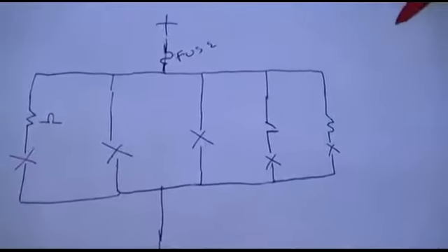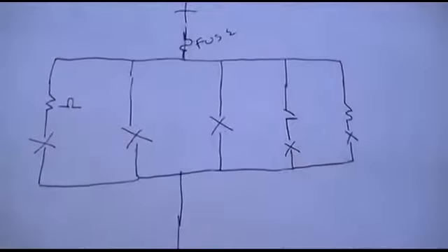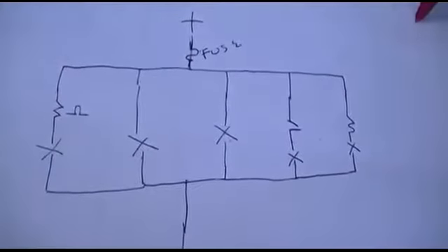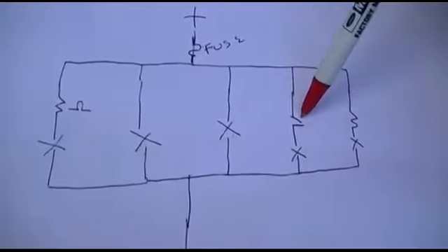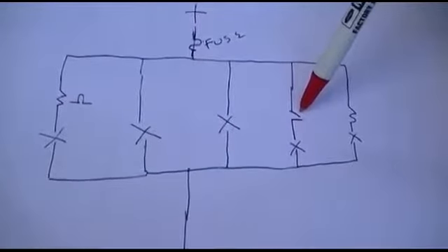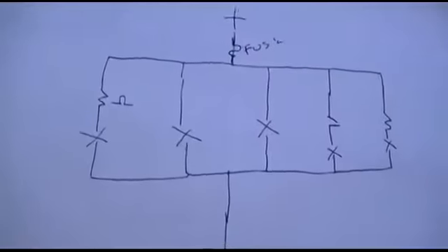So you can rule out pretty much right away the loads that have resistors. And you can rule out the loads that have switches that are disconnected when the thing is shorted. And I'll show you more of what we mean on the schematic for this radio. Let's have a look at how shorted this is.